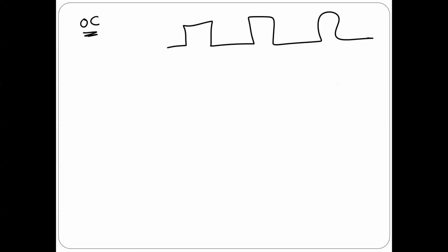The idea is that in chapter 3, as I explained last time, we took almost 100% of the CPU's time to generate the square wave. This time I'm going to take very little time from the CPU. I'm going to have 1 interrupt here, 1 interrupt here. That's all I need. So I'm not going to take too much time from the CPU. I'll tell you how it works, and how the counter is going to help me count this time.